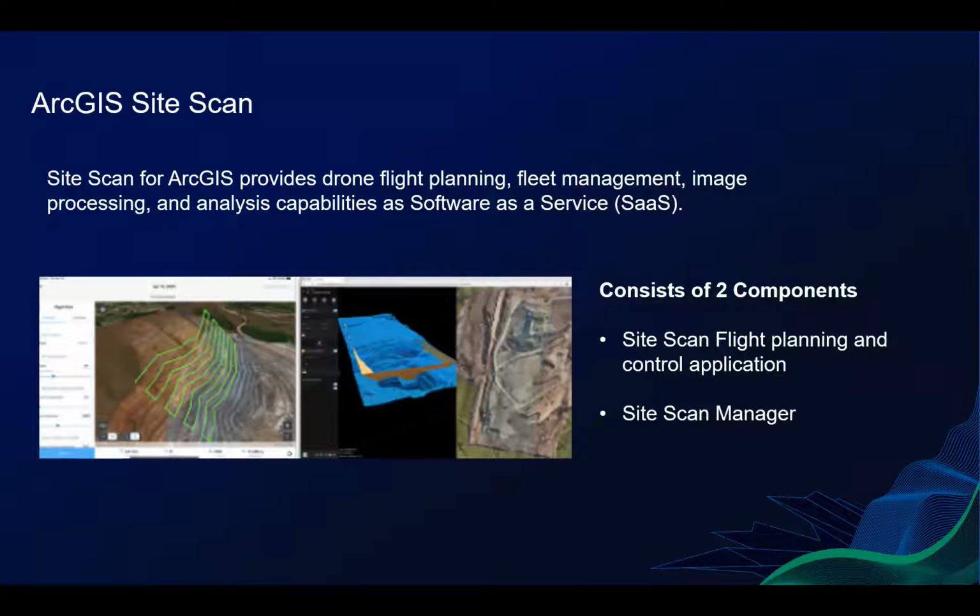And it has two main components. The first component is what we are calling the Sitescan flight planning and control application. This is mainly for before you do your flight planning and capture your images. And then we have what we are calling the Sitescan manager. With the Sitescan manager, this allows you to process your images, manage the drone images that you have collected, as well as analyze the drone imagery.